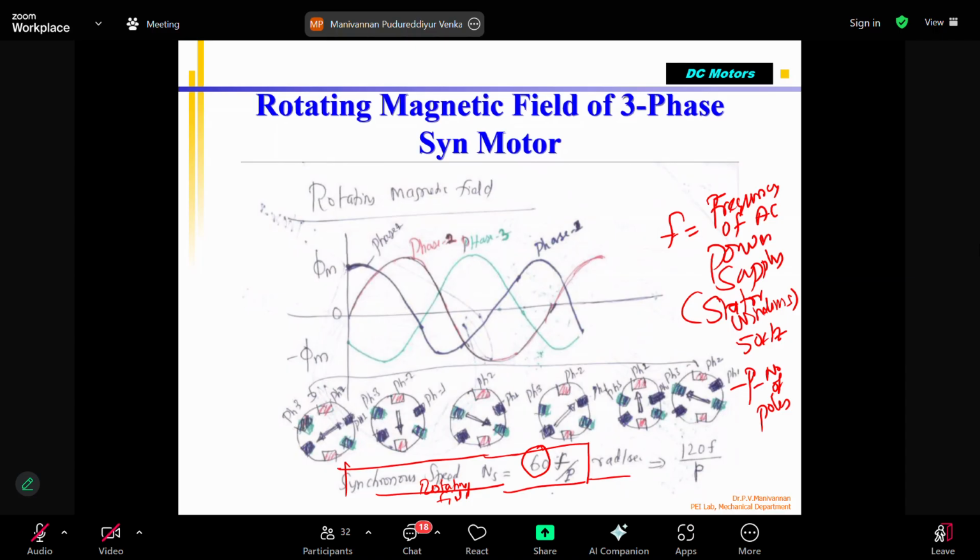You can see that in this formula I wrote capital P, and here I wrote small p. The capital P represents pole pair. How many pole pairs are here? This is one pole, the red pole, and this is another. Together it is one pole pair, capital P, 1P. And again I have a second capital P, then this is the third capital P. That means with pole pairs, I have 6 poles.